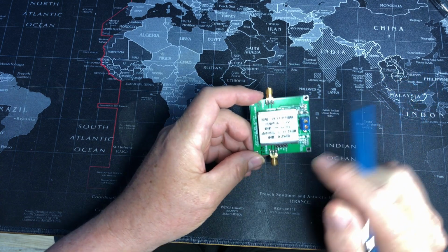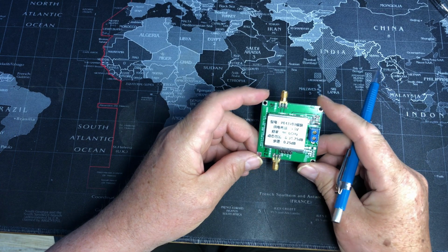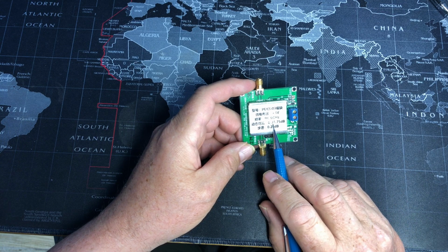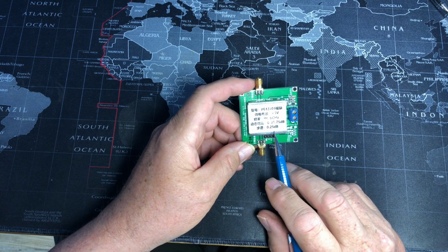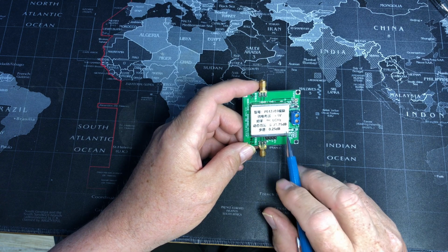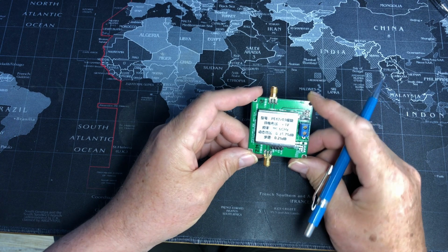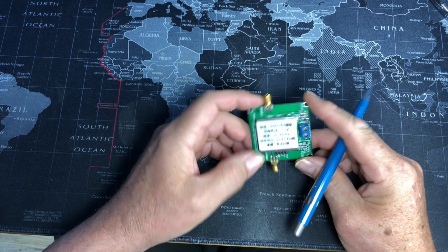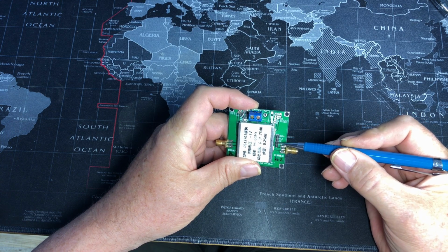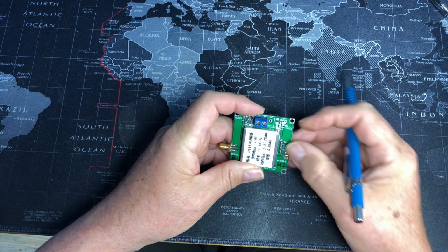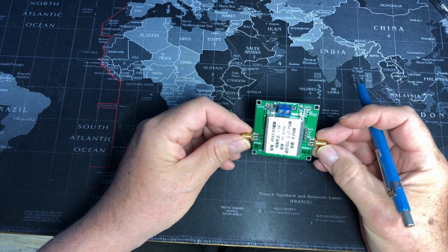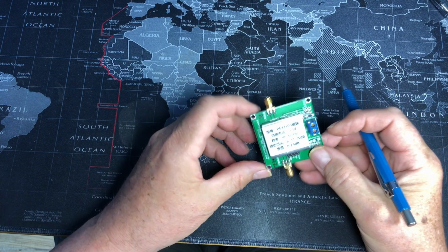So, pulling the data sheet out from that, this supposedly gives me a range of 0 to 31.75 dB in 0.25 dB steps. So ideal, really. And it's serial controlled, so we've got data, clock and enable. Perfect for hooking up to the Simple VFO hardware.